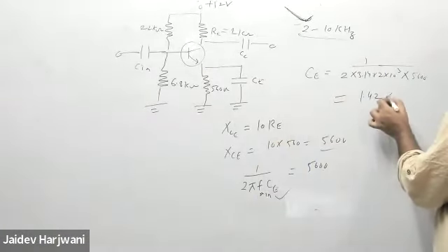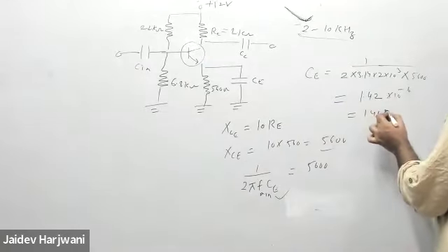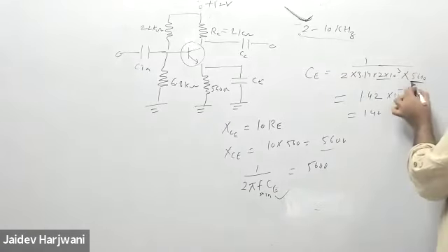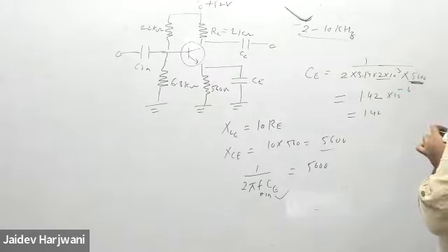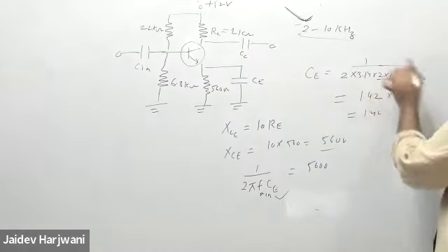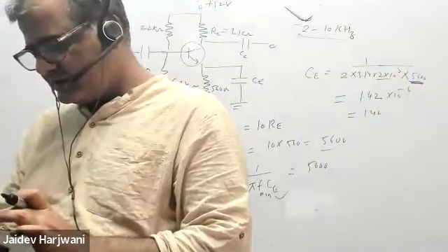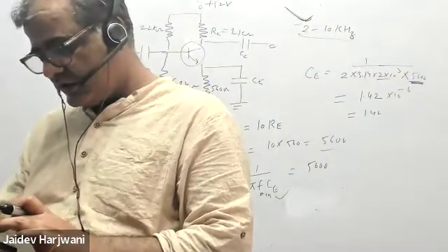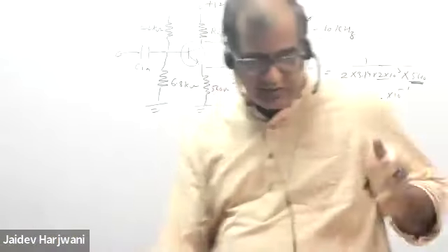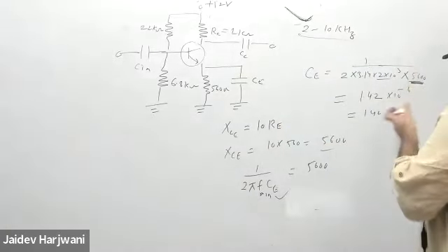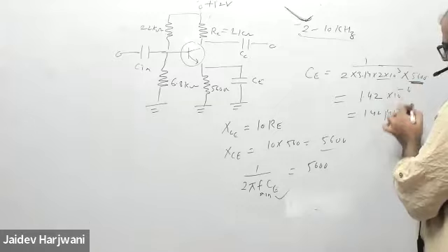This is microfarad. Check it, calculation you have to do it. We only use frequency in kilohertz, right? And the resistance was in ohms, this is 5,600 ohms, so 5.6 kilo ohm, but we use 5,600 when we divided. So what is the calculation? 1.42 into 10 raised to minus 5. That's what I'm telling. Either microfarad or millifarad, you have to check what is coming. So I have answered microfarad. You may check it.